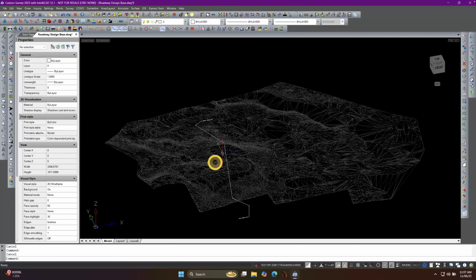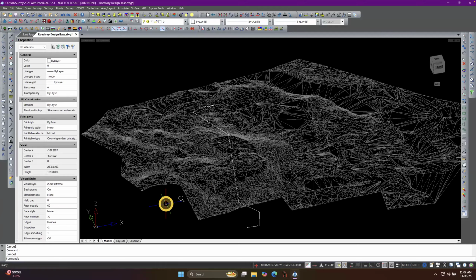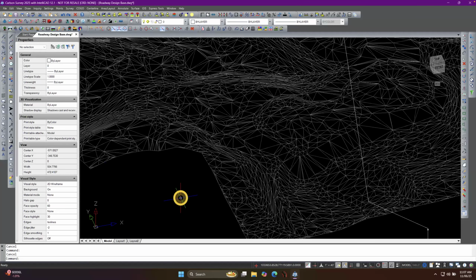And what do I see about that surface now that used to look like contours? Well, now it looks like triangles. Well, that's the way Civil 3D handles surface entities. You tell it how you want the surface to be displayed in these different conditions. One's in plan view, one's in profile view, and one's in what they call model view, or three-dimensional perspective view of the object.